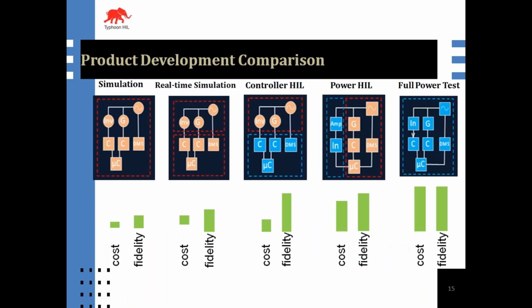These are the development stages. Now here you can differentiate what the simulation, real-time simulation and CHIL are, then power HIL, then full power test, according to the cost as well as the fidelity, how much comfort and flexibility you are going to have, and what the result approximation and actual results are that you are going to get.